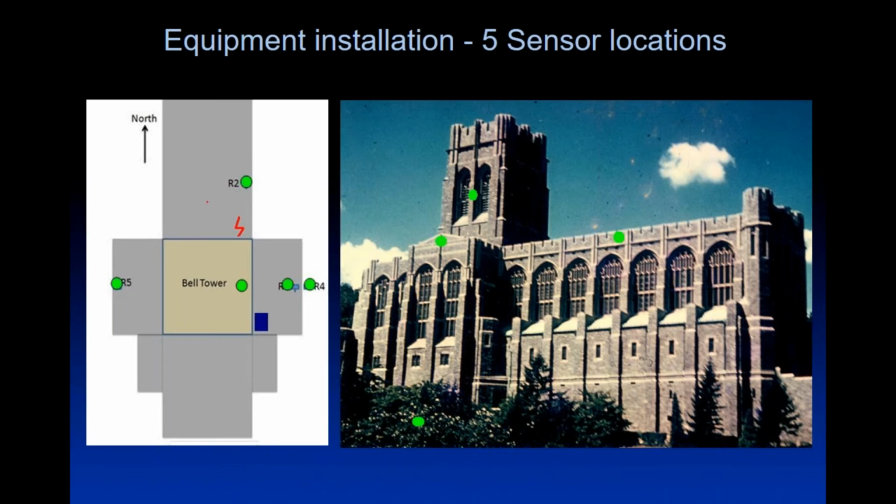But times 10, and you are up at the 5 inches per second value. That means you are almost certain to have damage. So we looked in detail at what was happening in the mode shapes and said the stresses are going to be greatest in between the transept, which is away from the measurements from the blasting, that's over here, and the nave. So we predicted that there would be damage already caused in this area here. So they went and had a look and found new cracking as a result.